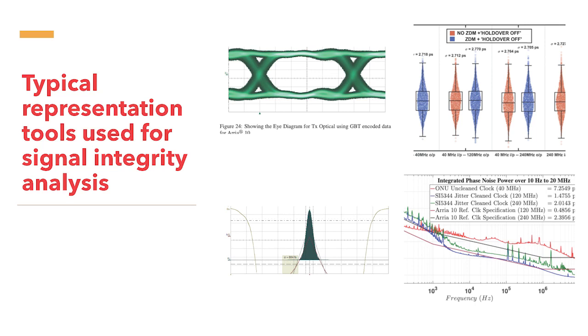The opening of the eye diagram gives you the quality of the signal. The eye height will give you any amplitude distortion, and the eye width will give you any timing distortion. And this part of the graph, where these two signals coincide, gives you the jitter information. If you zoom in, it will look like a Gaussian peak, and this is the jitter. The smaller the jitter, the better it is for the experiment.